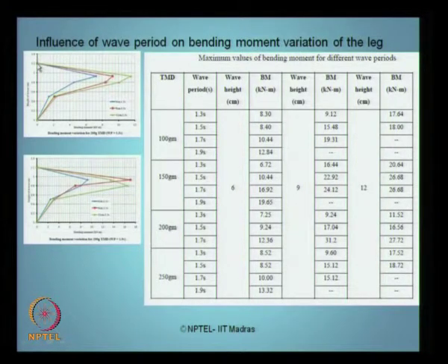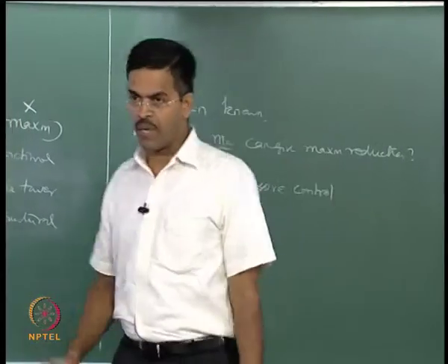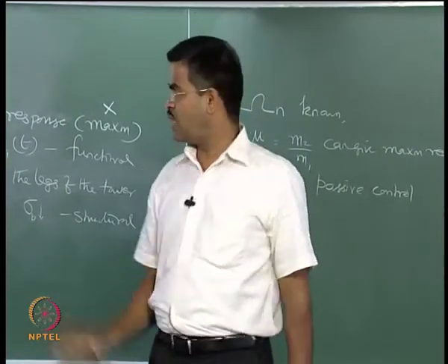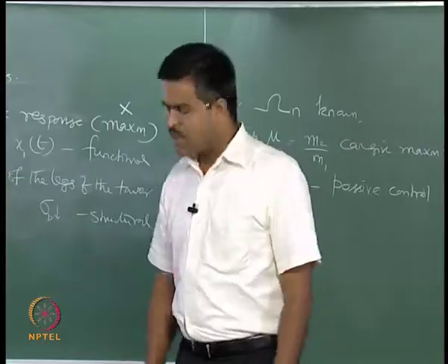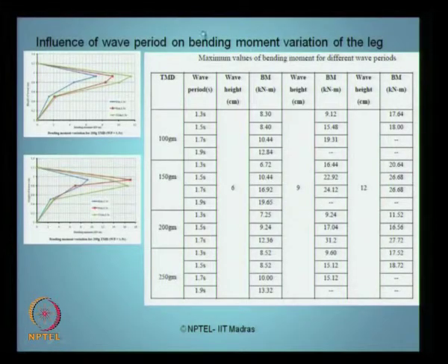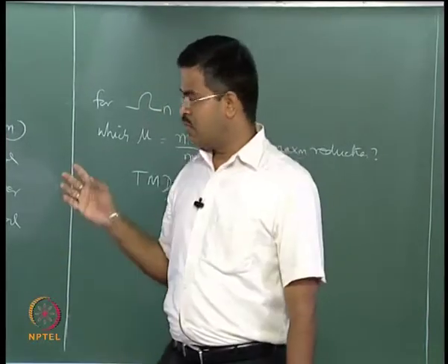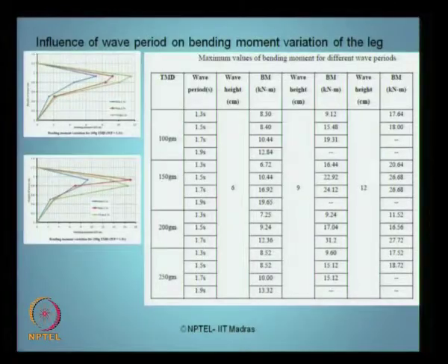this is the point where I have my top hinge which is connecting the deck and the tower. This is the point where I have my bottom hinge which is connecting the tower and the foundation. So, practically I have bending moment 0 in both these places. These bending moments are measured directly from the experiment. These are all experimental results, okay, and these are the points where they have been measured using strain gauges. The dots you see here are the discrete points where the strain was measured. From the strain, since the structure remains elastic, we have computed the bending stress. Okay. That is why the figure is not continuous, it is discrete, it is breaking, because these are the points where they have been measured directly from the tower.